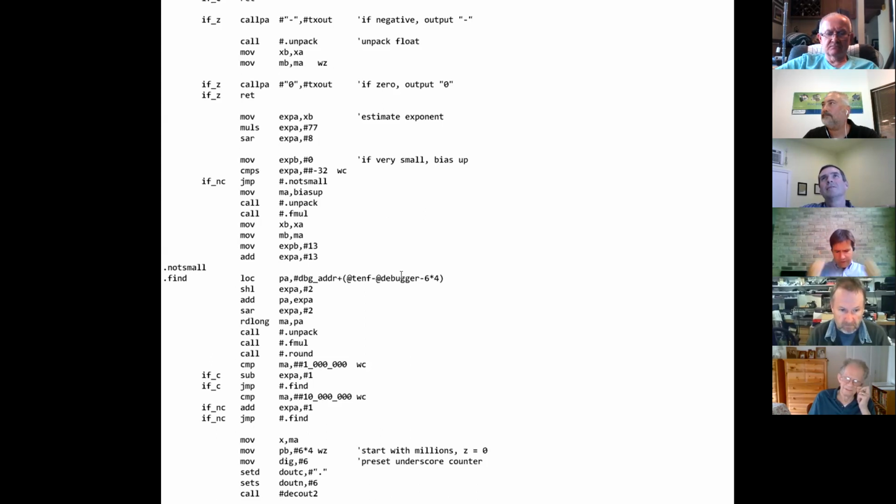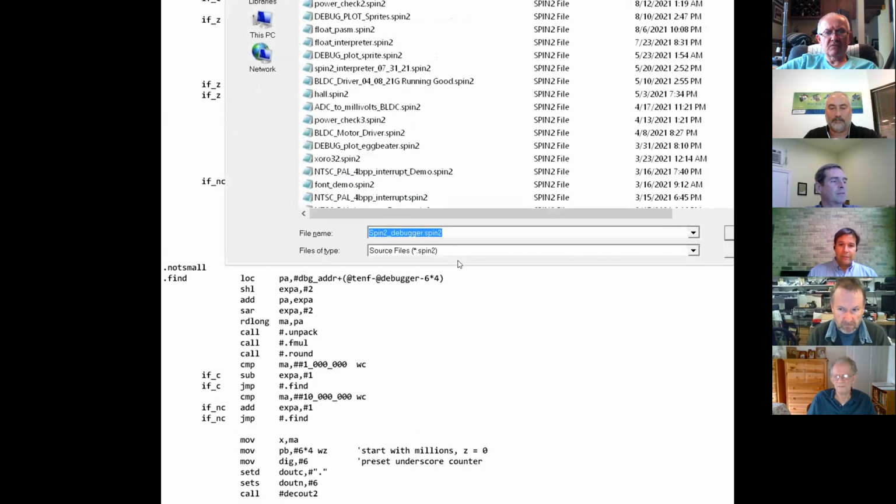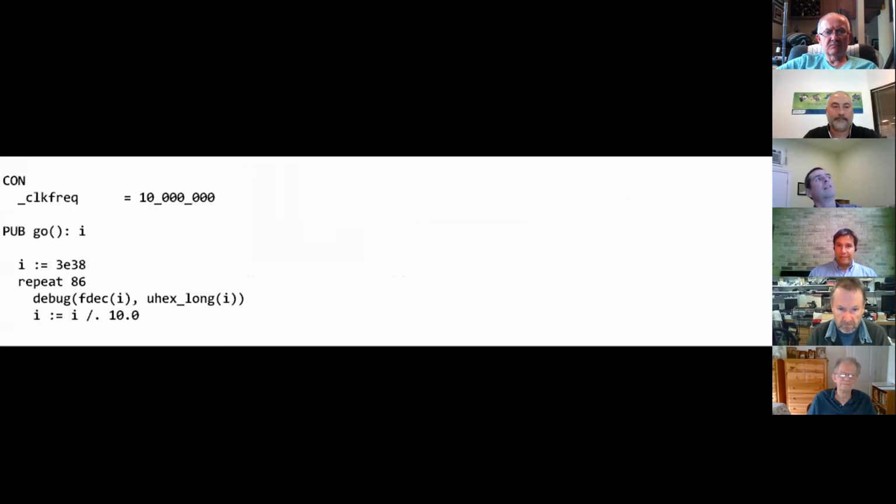Another thing I was thinking might be useful to add to the compiler in the Propeller tool is some kind of a flag that you could toggle on and off with a little checkbox under preferences. Because the number one problem I've had with the P1, without automatic casting, has been people accidentally mixing and matching floating points. So if somebody's using one of these floating point methods or floating point operations, plus dot or something, have the compiler and the Propeller tool do a sanity check that it's not some outrageously large number, in the hundreds of millions, if it was looked at as an integer.